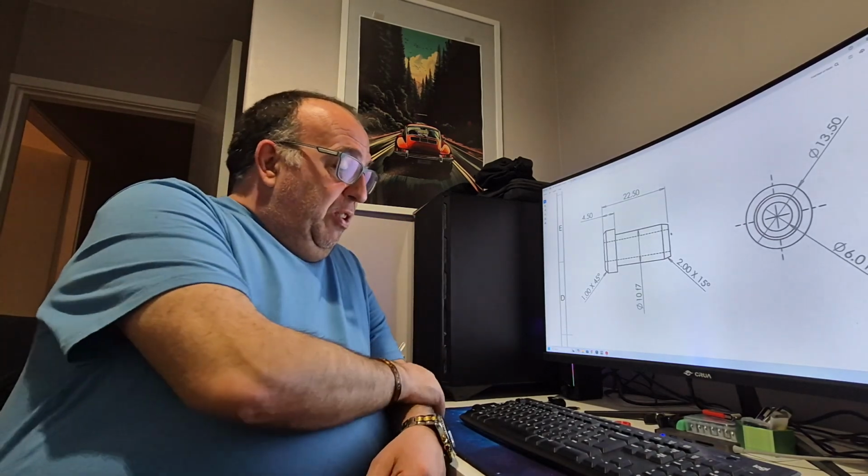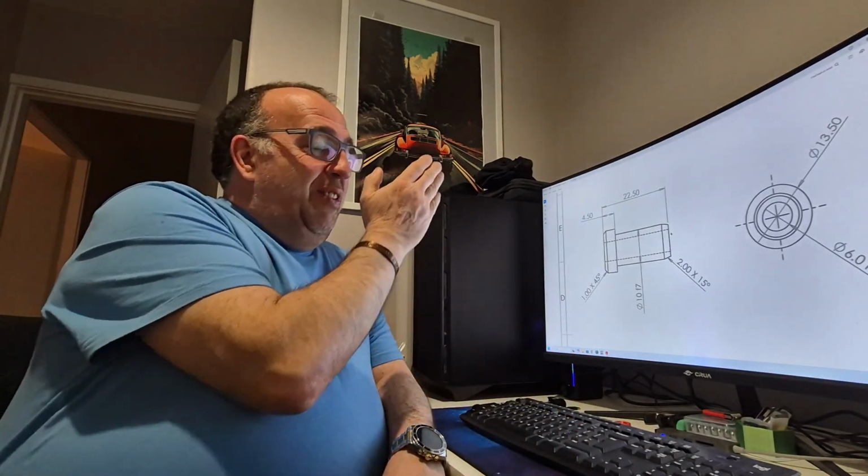We're not going to set up a secondary just to do a chamfer. We do that on this job. It's quite good. You start a job from the beginning, go all the way to the end, and as it comes off, it's actually complete. Minimal deburring where you part through the workpiece into the hole. You need to clean some of that up because you're not going to avoid it.